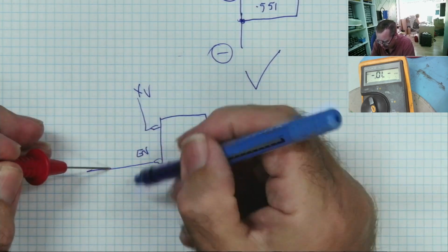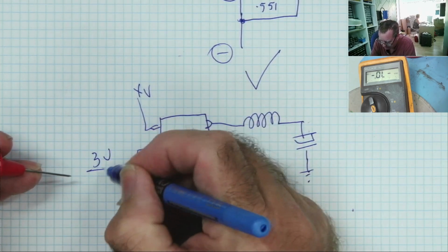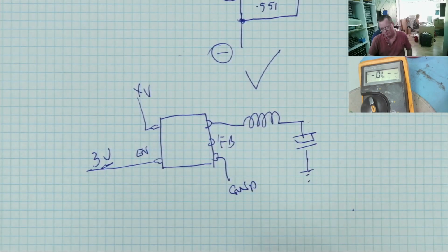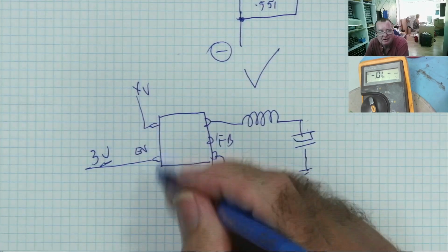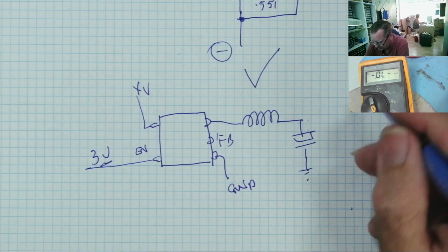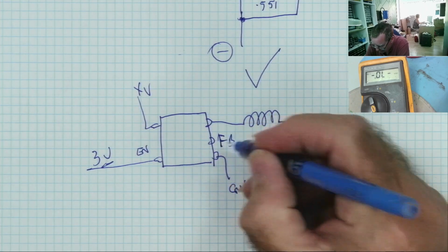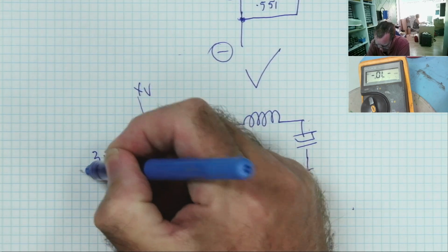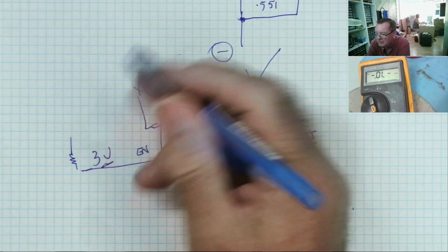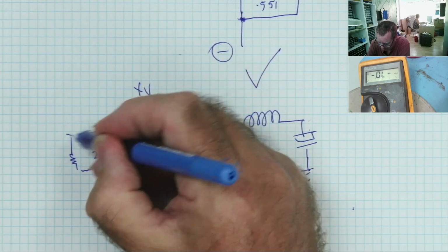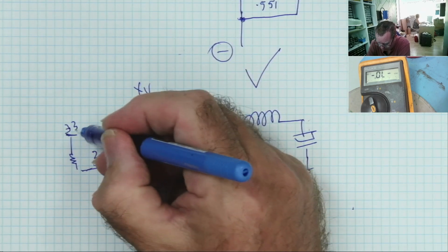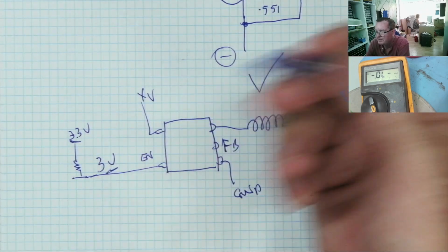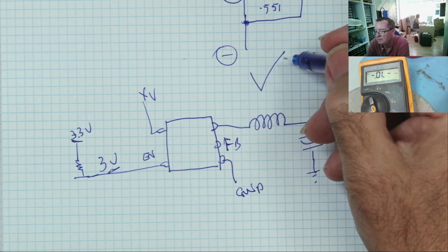And what you're doing is you're putting about 3 volts in diode mode onto the enable pin, and you can switch that chip on. Okay, you can switch that chip on and see if it runs. So that's another possibility. This is for faults where, for example, there may be some pull-up resistor here up to the 3.3 volt supply or something like that, and it's floating and you're not getting the pull-up, and this is just floating, it's not switching on.